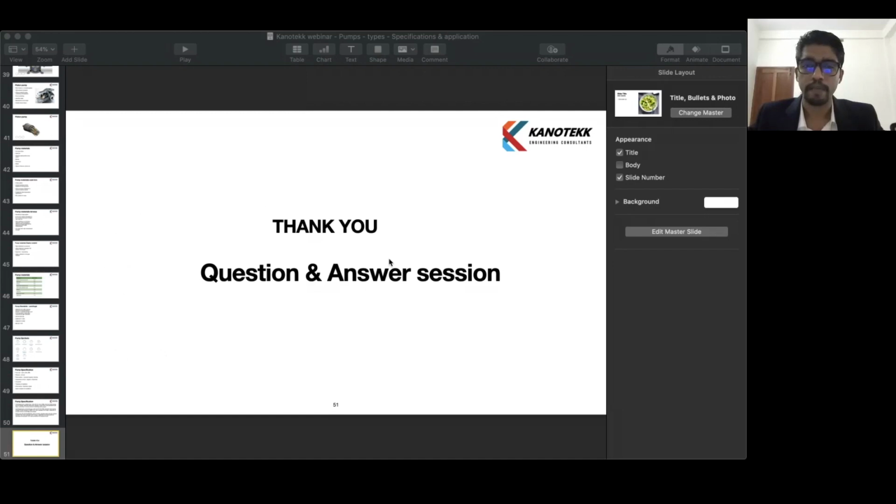When we select a pump before ordering, you can ask them to calculate the NPSH available and compare the values with the NPSH required, which is specified in the pump data sheet. We may get 5 or 6 offers generally through the procurement department. These offers we compare with the NPSH available, which helps us to select a pump which meets the requirement of the margin.